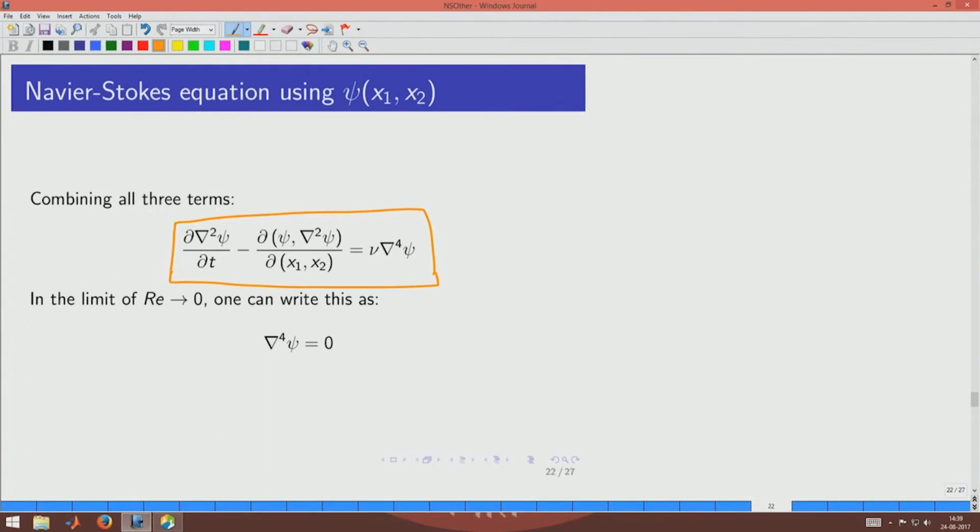Now, we can also see that from the discussion on Reynolds number, that the diffusive term is going to be governed by the Reynolds number, and if the Reynolds number is small, the diffusive term is going to be playing more role. So, in a situation where the Reynolds number is very small, how can I approximate this particular equation? You could see that the Navier Stokes equation is approximated to such a simple form. Okay. So, this also will be given a name, Stokes equation, and we will see that Navier Stokes equation comes out to be a very simple form in the limiting case of Reynolds number being very close to 0, which means basically creeping regime.